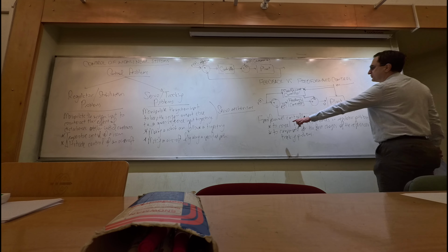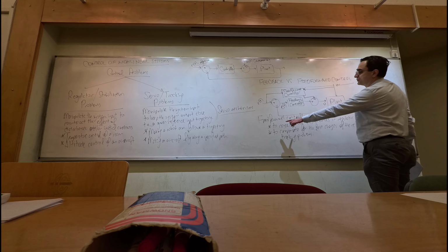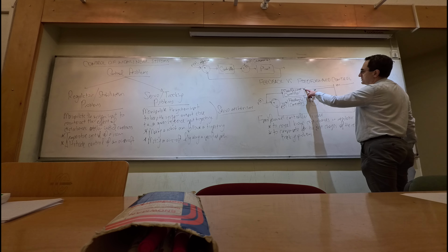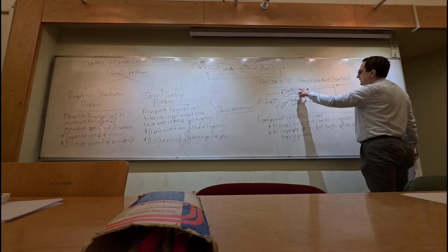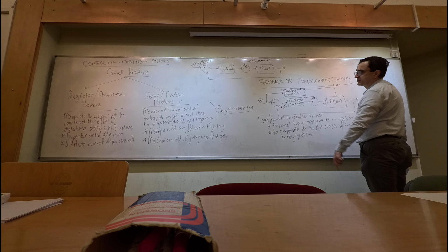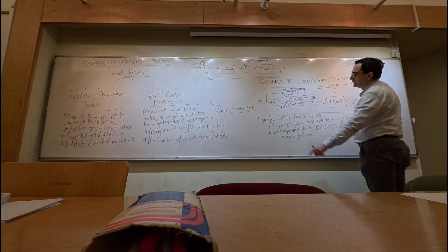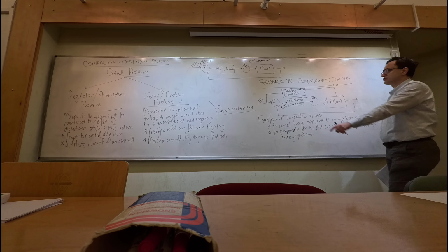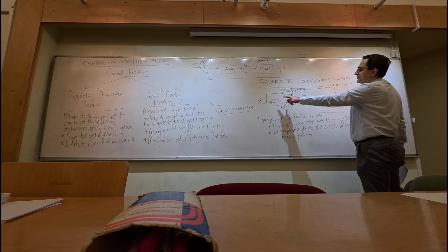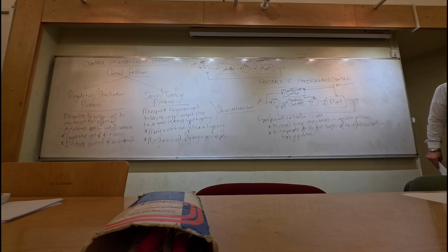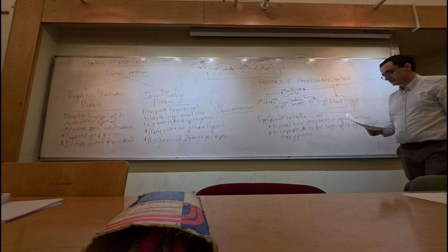The first thing it can be useful for is to cancel known disturbances. If it can take measurements from the disturbance, then it can help cancel the disturbances in the control system. In a servo problem, it can get measurements from the reference input, and then try to compensate the effects of the fast-changing reference input in the feedback loop. That is the second task.